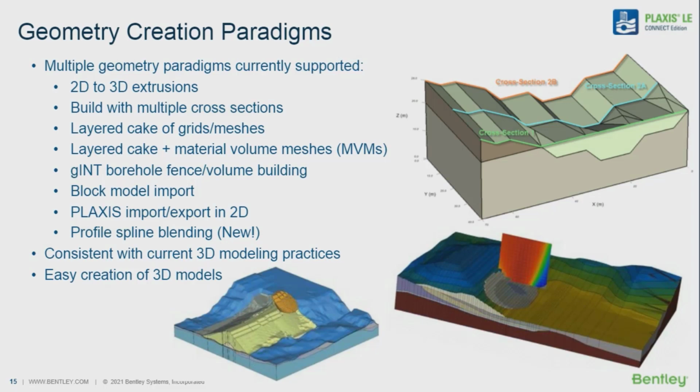Use boreholes to interpolate the virtual borehole representation. Let's say you work in the mining industry, you'd like to bring the block model in order to perform a slope stability analysis. Well, you can bring the blocks in PLAXIS Designer and also in PLAXIS LE as well. So PLAXIS import and export in 2D. We mentioned the possibility of exporting the geometry to PLAXIS. And profile spline blending. We'll see a demonstration.